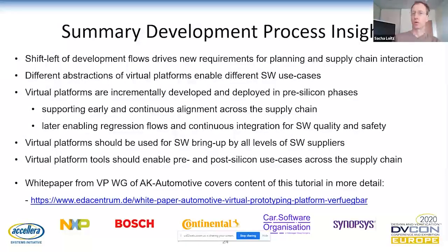Therefore, the timing is, with certain restrictions, of course, important, and needs to be respected, as otherwise some tests or security measures that the software needs to take in order to reach the ASIL level will fail on the virtual prototype.